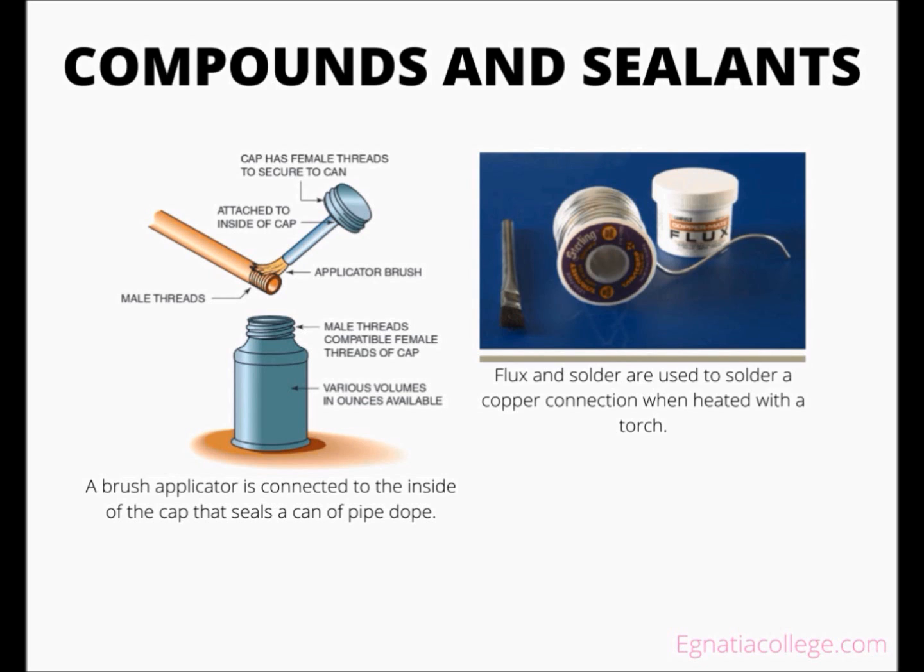Plastic piping uses a solvent welding process that requires a cleaner, glue, and primer to create a permanent connection. Each of these basic connections is unique. A plumber can connect different types of piping with threaded connections. Pipe dope is used extensively with metal threads, and Teflon tape is used for both plastic and metal threads.